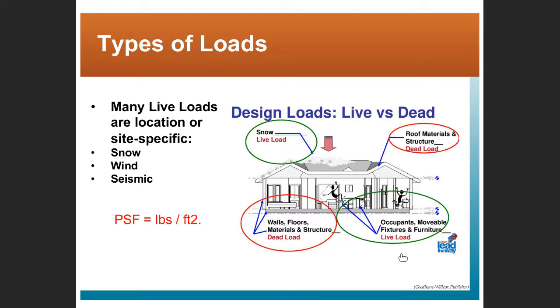But we also have to contend with other live loads that are more site-specific, right? Snow is a live load. That would be site-specific. Wind would be a live load that's site-specific. Seismic would also be a live load. Seismic means earth movement in the case of an earthquake.